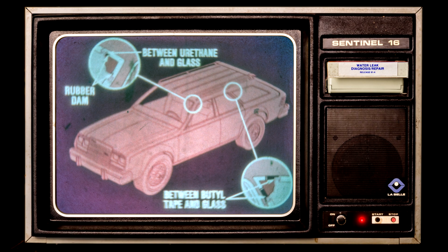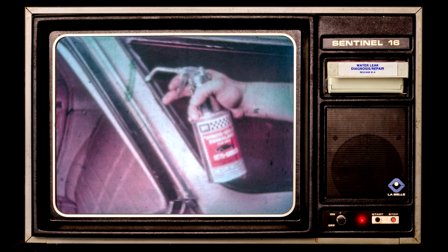Probably one of the most misunderstood types of leaks are those that develop at windshield or rear window glass seams. Some glass is sealed with urethane and some with butyl tape. Leaks at these 2 types of sealers require different fixes. 2 products are recommended for leaks in the butyl tape applications: 3M's Window Weld Resealant or Kent Industries Wet-Dry Resealant. These pump-grade sealants, which flow easily into pinholes, adhere to glass or painted metal. They dry fast, forming a flexible, rubbery seal.